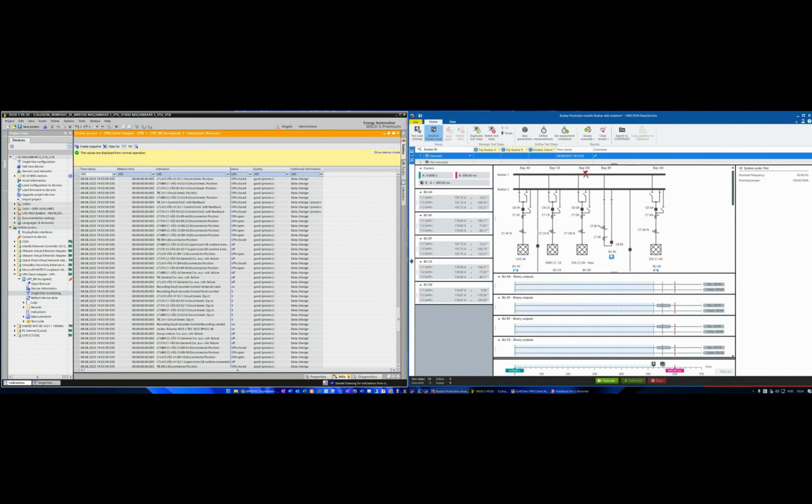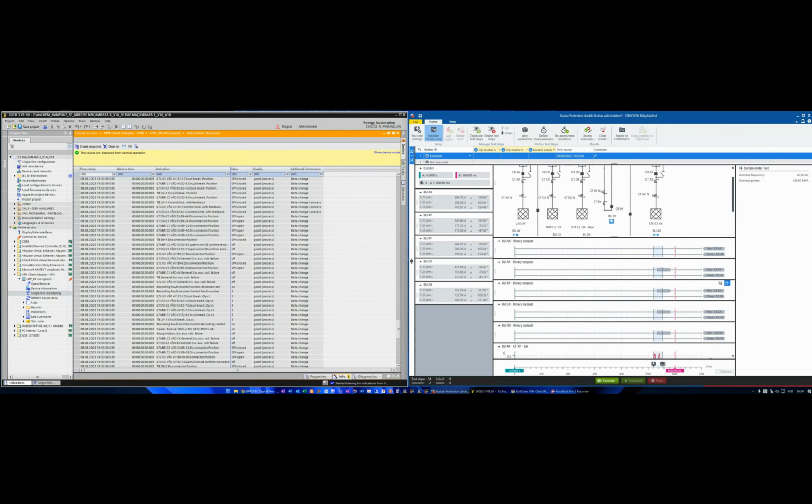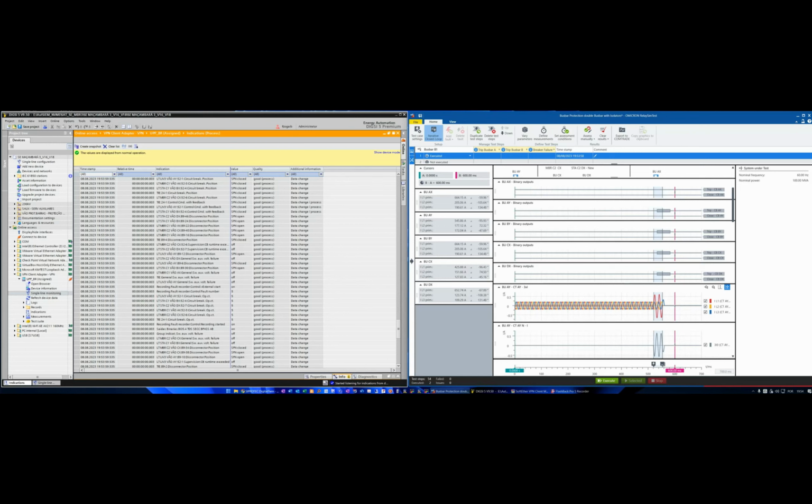So what I have done here, you can see the response of the relay, the SIGRA syntax, and we can see the steps. And this is very good to see because here the relay created another step. I can say this because there was the fault, and this fault was cleared, and they showed here the consequence to clear.